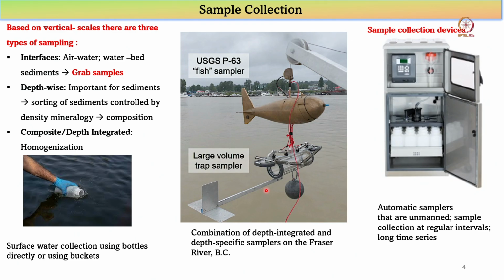So water again gets slightly, velocity of the water slows down near the bottom. So therefore, the highest maximum velocity is somewhere near the middle of the depth. Okay, so in rivers, the depth of the stream also varies with the hydrograph, right?